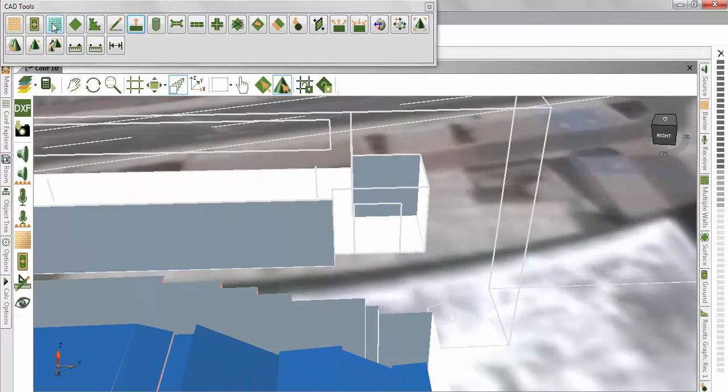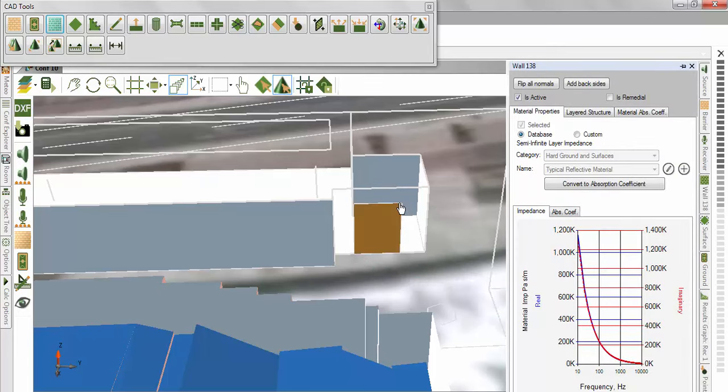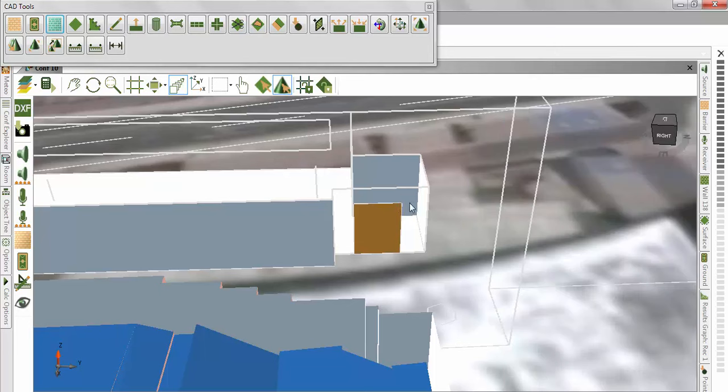We will now draw our door using the Create Wall tool. Just click on the first 2 points of the door width and right-click to finalize your wall. Then drag your mouse to define the height. To create the surrounding wall, use the Create Surface on existing points.